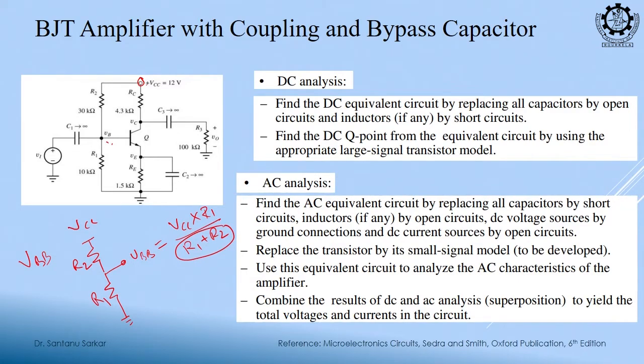Okay. So, I have removed one voltage source, done, the input side is done. What is the meaning of DC biasing here? To find out the proper values of R1 and R2, so that you arrive at a proper value of VBB, so that the base-emitter junction is forward biased. Then what is your objective? The first objective was to find out VBE, right, then find out IB, then find out IC,